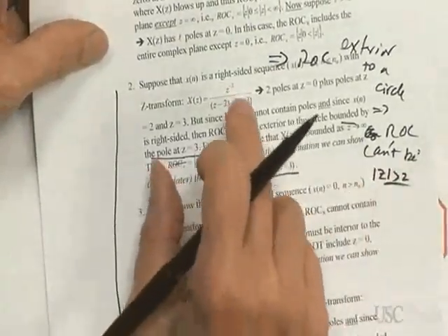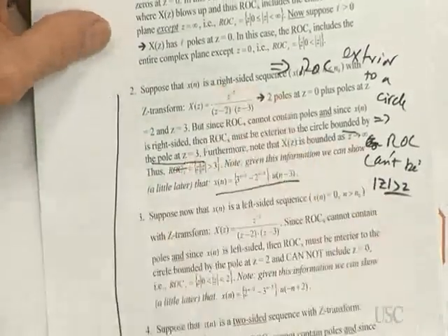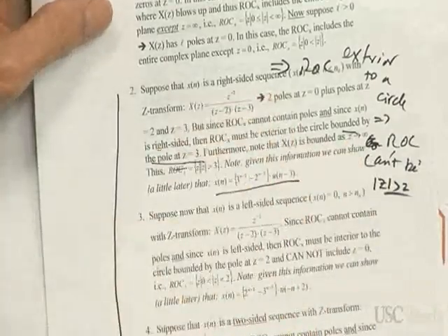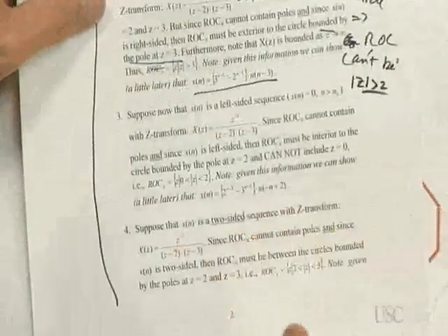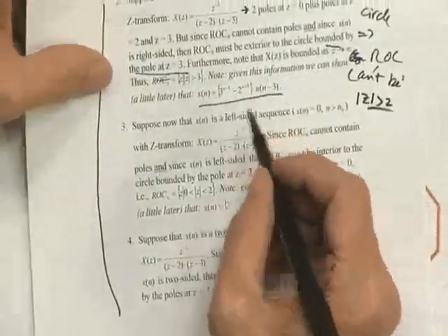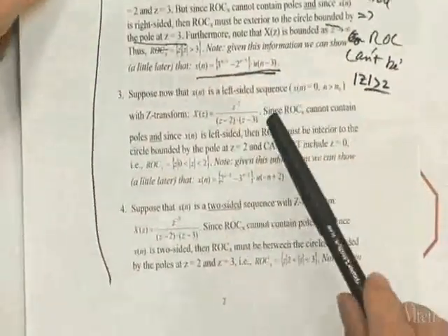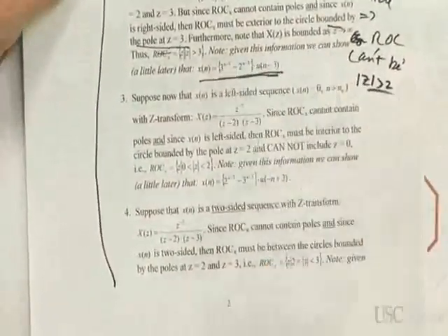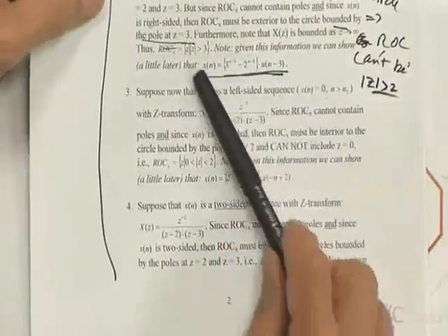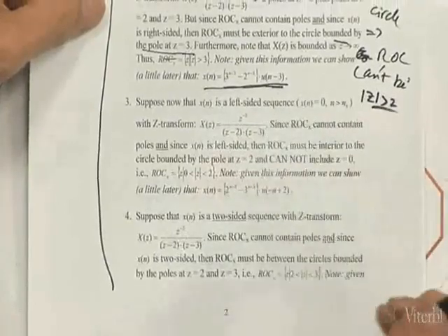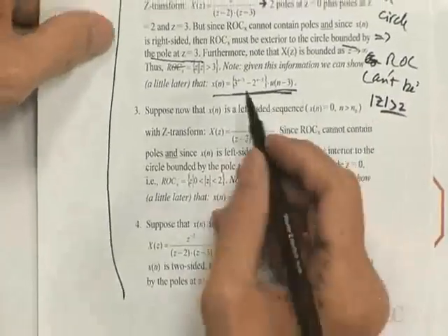So you know what I can tell you about the inverse Z transform when you find it? It's going to blow up. Inverse Z transform, the x of n, going to blow up. Won't be stable. Why? Because the unit circle isn't in the region of convergence, see? And sure enough, if you look at the result, I'm just showing you the result here. I'll derive it later. Sure enough, it blows up. Blows up real bad.